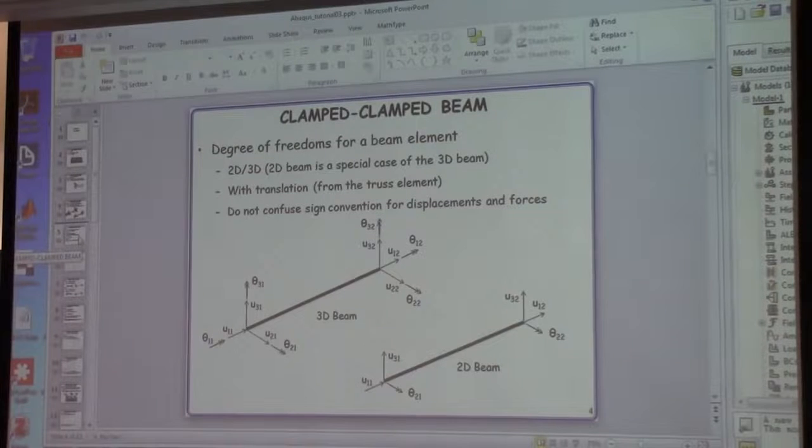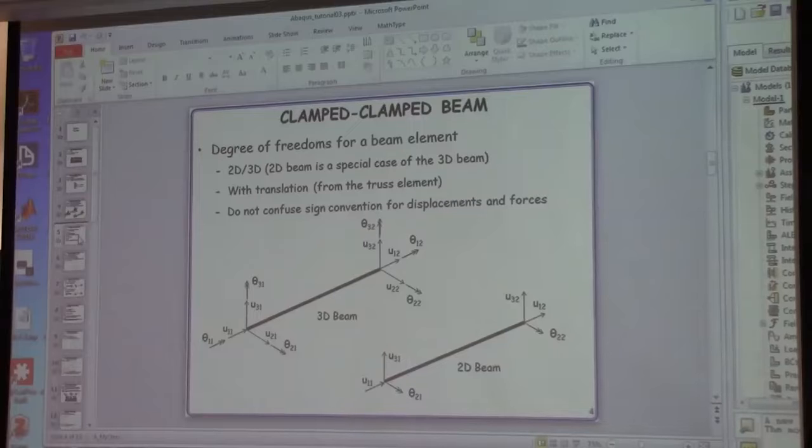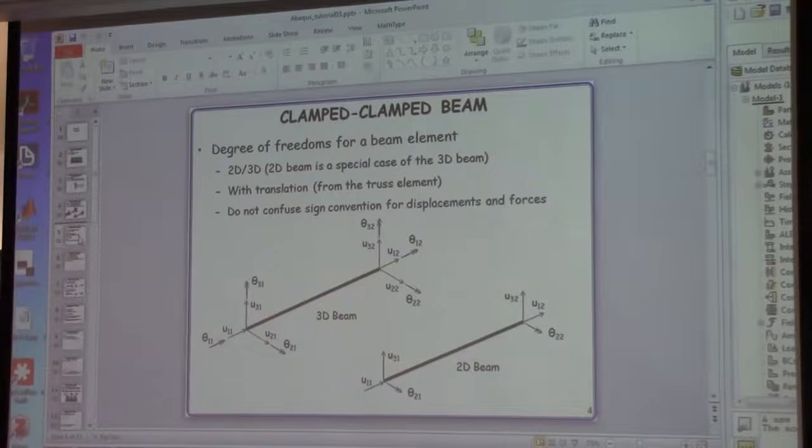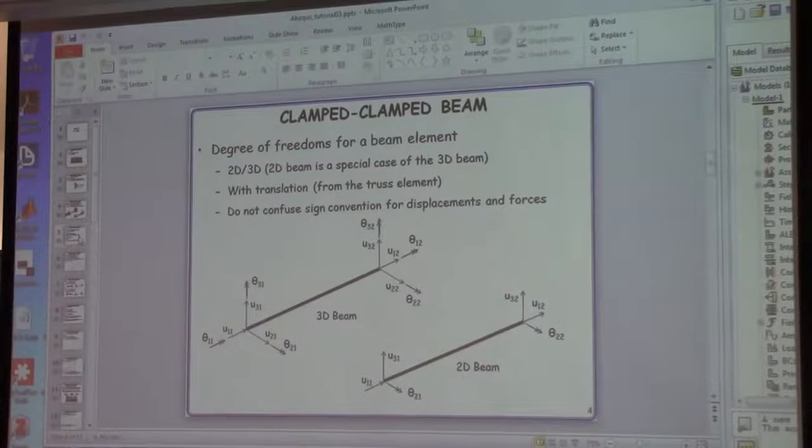And also in the truss problem, because we only have the axial force, the results we probably need to know are elongation and sigma xx, right? But for the beam problem, once we have bending, we have the bending moment result and the deflection, the displacement in y direction, and also the sigma xx is kind of different.